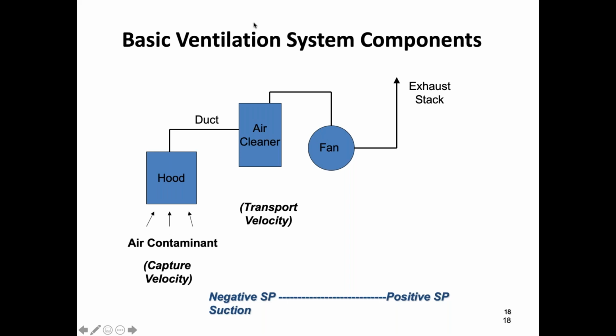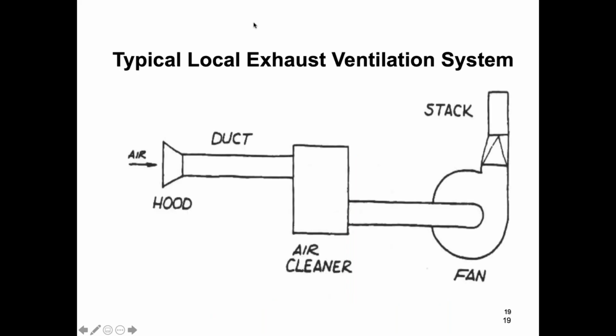So a lot of times that'll be before the fan. And then the fan, once you get to the fan, now you've got to get it outside the building. So the fan goes somewhere else, goes up, maybe goes up outside of the building, and it goes to a stack of some kind, like a small chimney. A lot of times there has to be a certain distance above the building, so you don't want that stuff accumulating on the roof if you're exhausting it outside, or getting sucked into a fresh air intake or something like that, if you're not using that kind of thing.